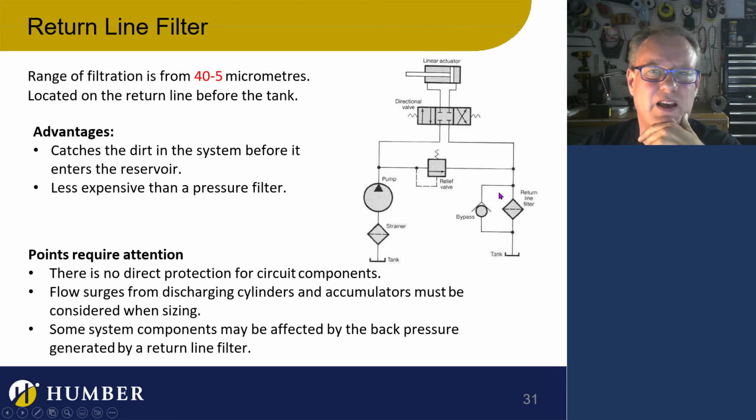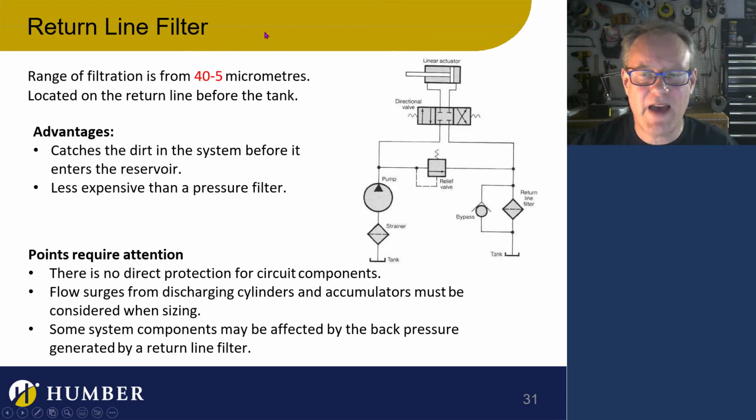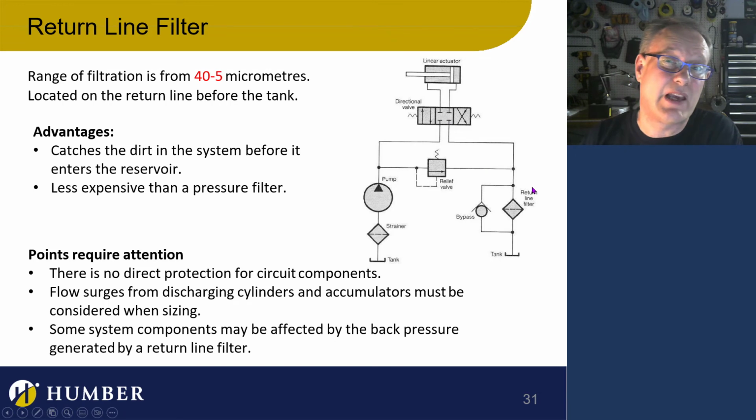Where does the 80 psi come from? The fluid coming out of the actuator, isn't it supposed to be at 0 psi? It's just flowing to tank, right? Well, yeah, but there's pressure pushing it on this side. If it was blocked, large pressure would be generated on this side, right? So it is blocked by this, but only to a small degree, maybe 80 psi.